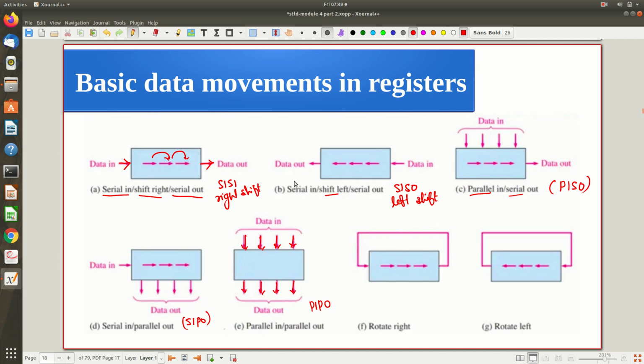But instead of that, you can think of a rotation where, whenever you are doing this right shift, instead of discarding the least significant bit, you can feed it back to the input, the MSB position, so that there is a right rotation. The information is moving right, in the sense of anti-clockwise, right? So anti-clockwise movement you can see. Similarly here it is left rotation, the information is moving in a clockwise way. So that also you can think of as a variation.